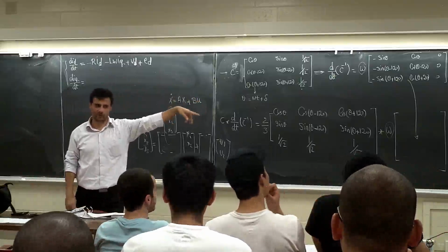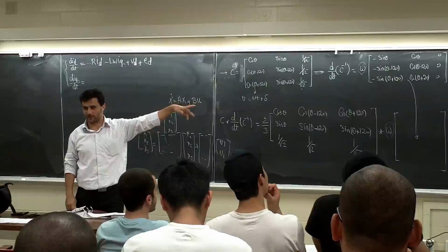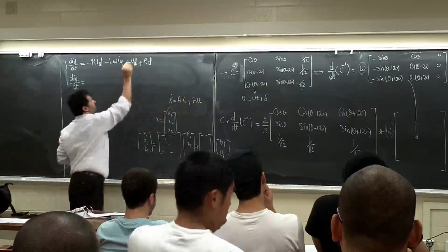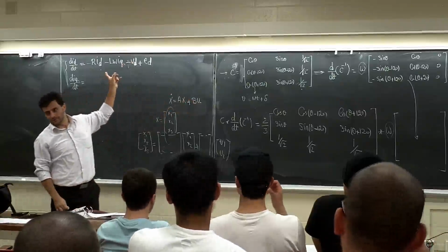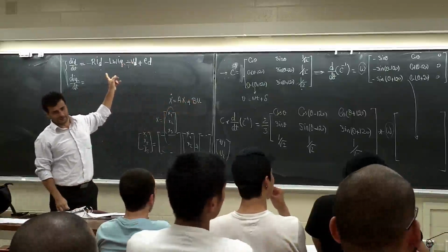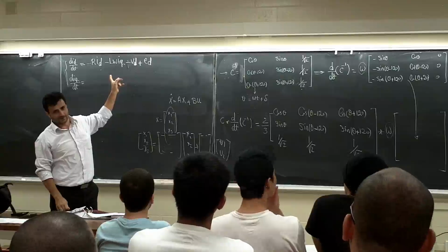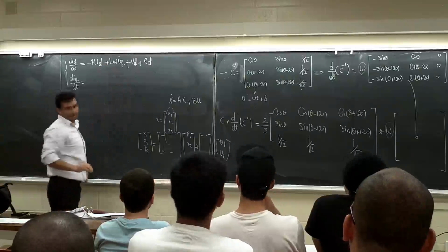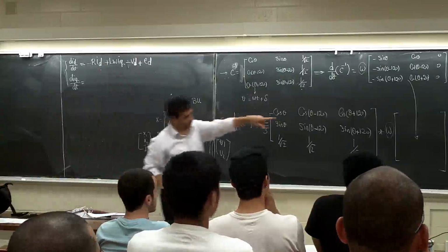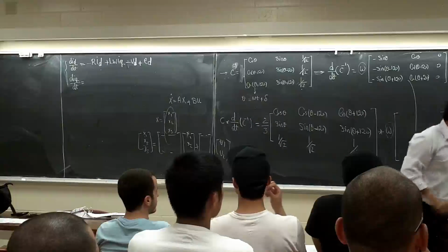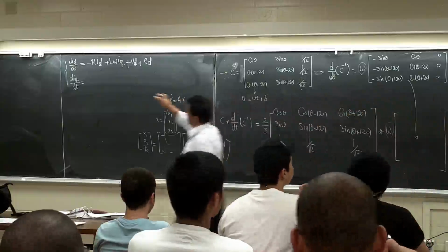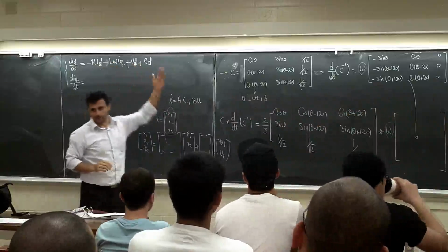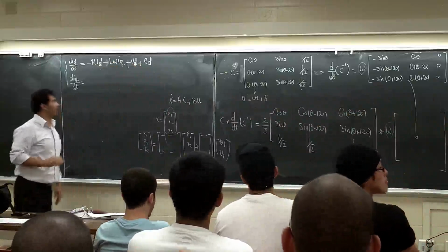I think you will check this, but you do need to know the state space variables. When it comes to this side, this one is going to be minus, right? And one more mistake here. Which one is wrong? Not all of them, just this one, the minus L omega IQ. Is it minus or plus? So it's plus. The rest are correct: minus VD plus E, divided by L.